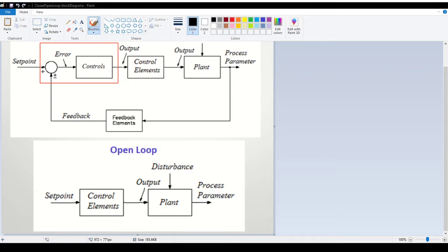Now, a step response means that the input or the set point is at one value and goes directly to another value. So you make a change. The most common is what we call a unit step response, which starts at 0. So we're putting nothing into the system, so the system is basically at rest. And then we go to 1 unit.